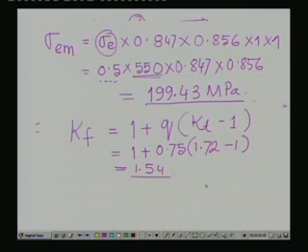Now, it is a simple situation where we can put all the values in the Soderberg equation, with this Kf, and sigma endurance for this one. We require sigma A, which we have already computed, and we have to put in the value of sigma m. What more do you require?